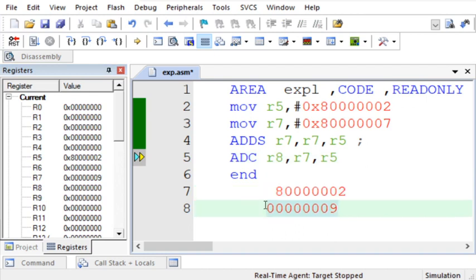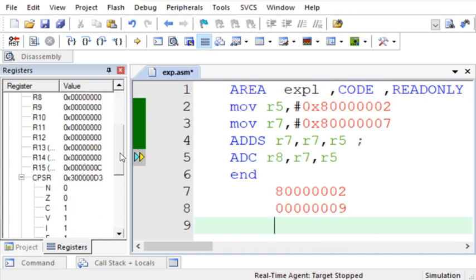Okay, now it is not only adding these two numbers, but in the instruction we are showing only two registers, that is R5 and R7, but the instruction says that we should add with the carry. So we should check what is the carry bit. Carry bit, we know that it is 1, right? So if we are taking that carry bit, 1 also we should add with this.